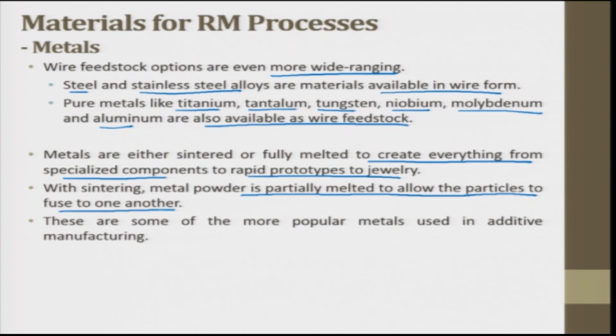Sintering can also be used here, as I said. In sintering specifically, there is direct metal laser sintering. MAM is metal additive manufacturing, and this is direct metal laser sintering, which is one of the MAM processes. This partially melts many different metals and alloys, yielding objects with a degree of porosity. So this can be one of the processes.